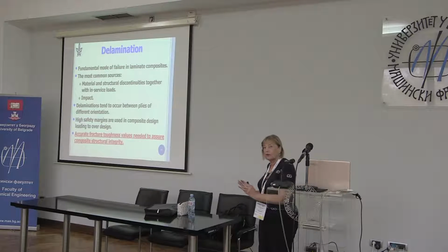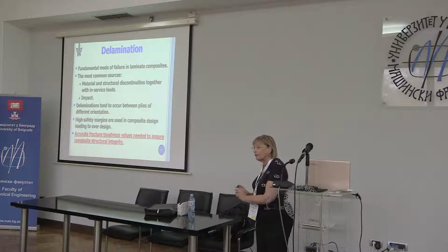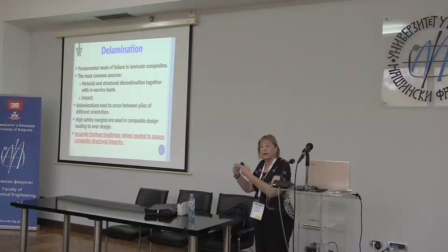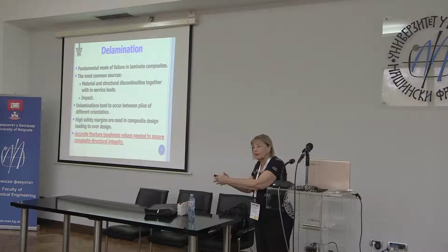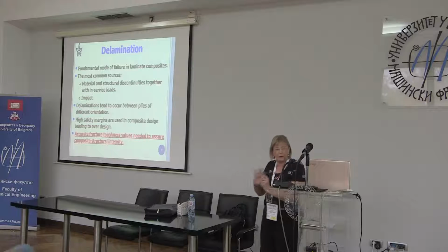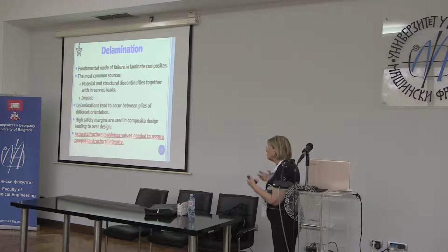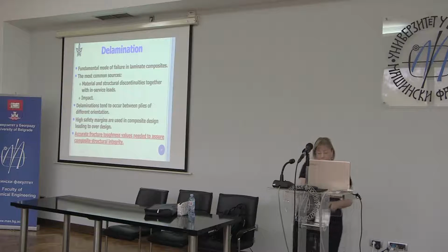We need the fracture toughness to talk about catastrophic conditions, and we also need fatigue data, and we would want to go in what's called a damage tolerance direction. There are problems with that. I'm not going to go into that right now, so I'm only going to talk at this point about fracture toughness, and if we can give accurate fracture toughness values, we can aid in predicting failure, as we do with metals.